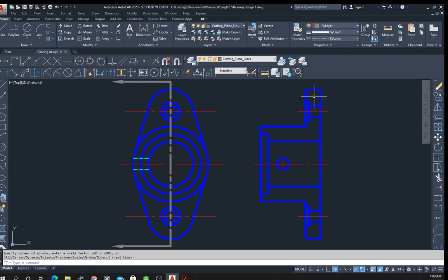Okay, so as I said, we need to select and decide which areas need to be hatched. So the hatched areas will be the areas that when we do the cut, they'll be physically up against the cutting line. And those areas will be this area here.